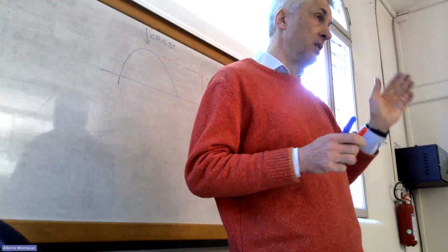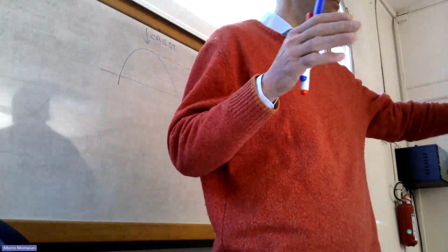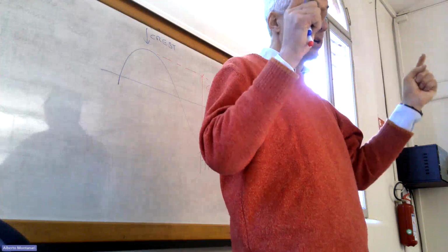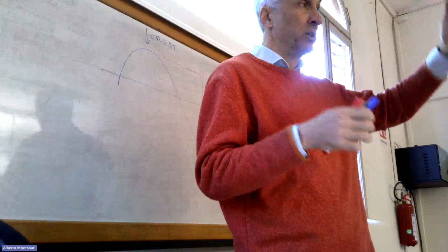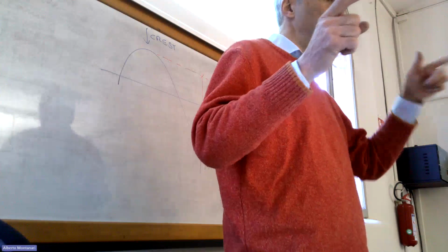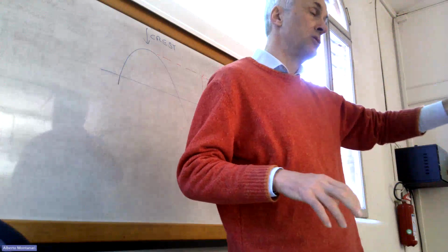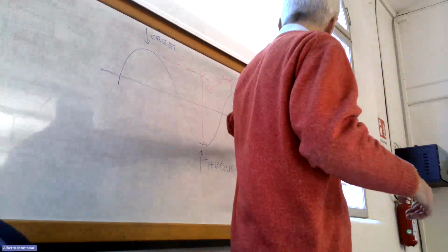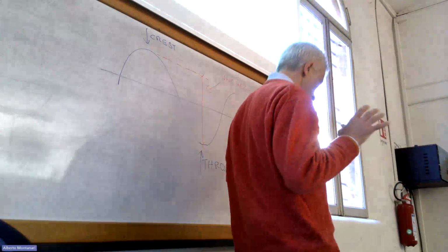Or if you are interested in only the max value of wave height between April and September, you can pick up from your data the max in the block April-September for each year. Okay, so if you have like 30 years of observations, you get the max from April to September in the first year, and so on. And then you get 30 values. And then on these 30 values, you estimate a probability distribution, which, depending on the reference period T, gives you the design wave.